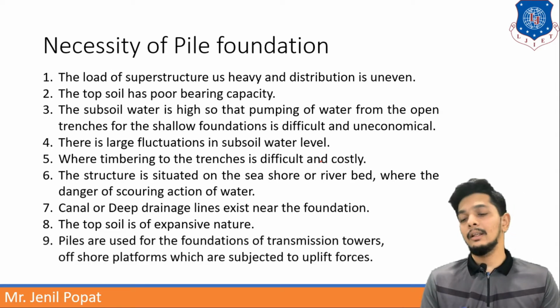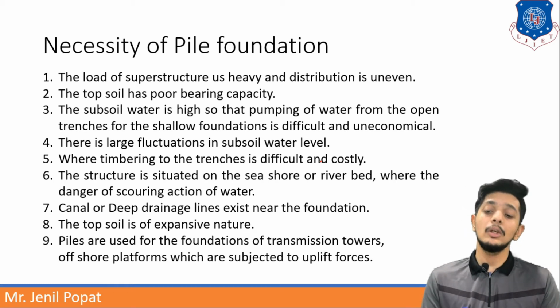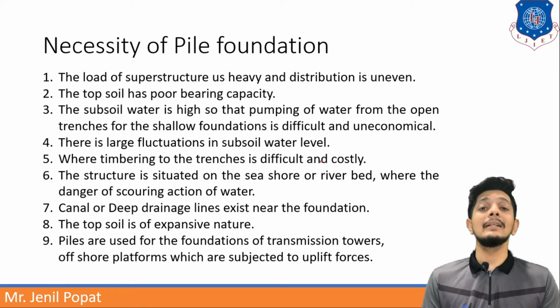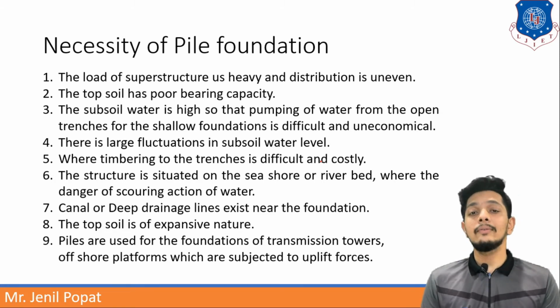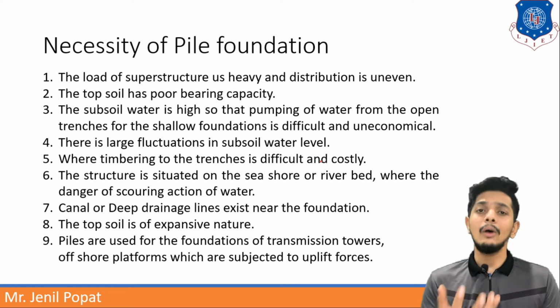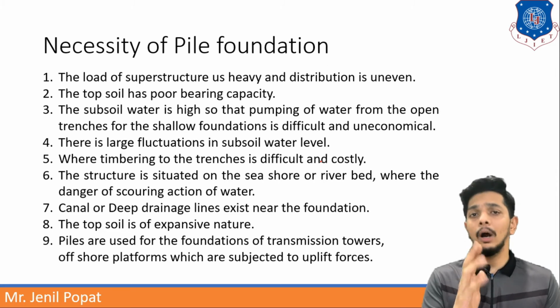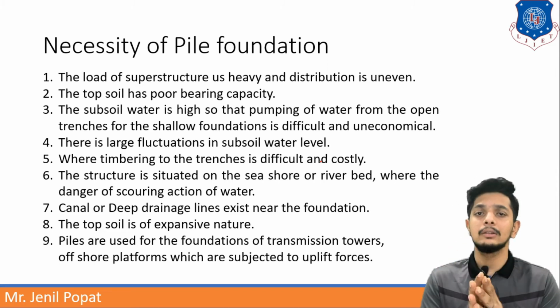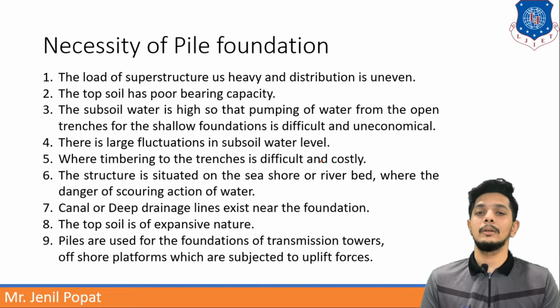And the last point is piles are used for the foundations of transmission towers and offshore platforms which are subjected to uplift forces. So piles are also useful and important against uplift forces. If the downward soil is taking your structure upwards, then it is an uplift pressure or uplift force. In this case, you should also opt for pile foundation.